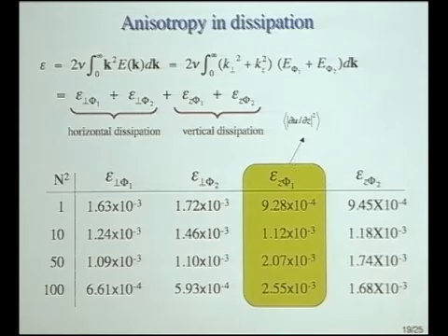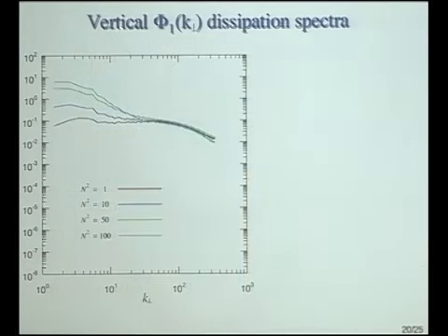And so actually, if stratification goes bigger, the dissipation becomes bigger. And actually, this dissipation is related to the vertical shear of the horizontal wave component, velocity component, and which is local Richardson number something.